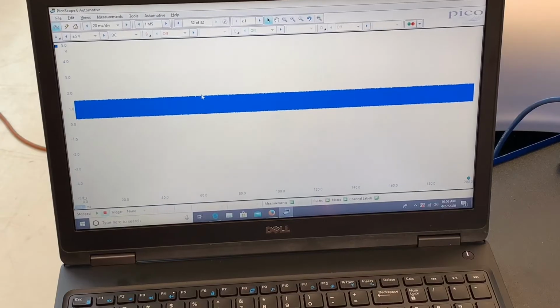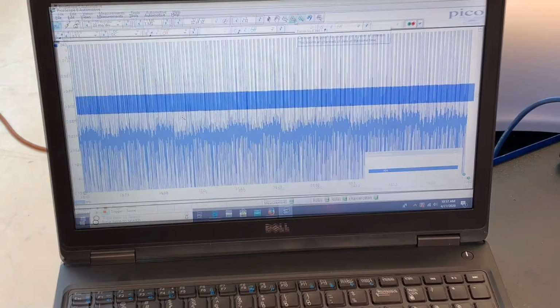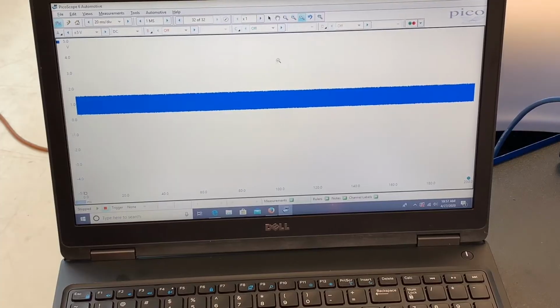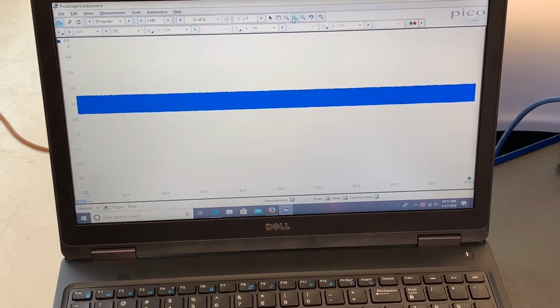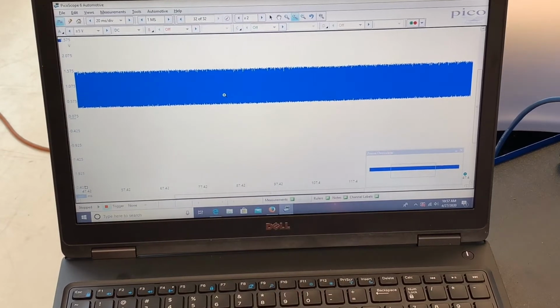We'll go ahead and pause one of these and zoom in so we can get a closer look. So again, this is on a low voltage scale. It is still digital communication. So here, this was some communication with the ABS module. So we switched over to one of the other modules on that daisy chain. And from here, it looks like a lot of noise.